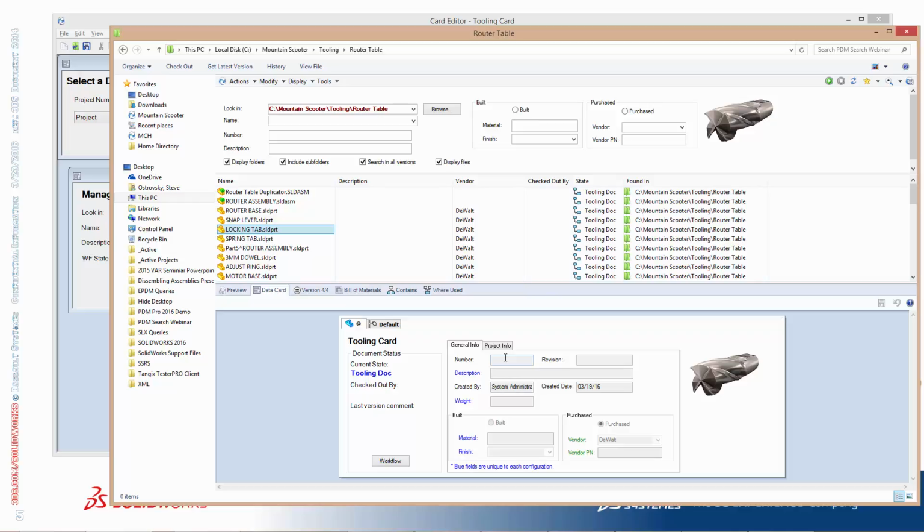I actually built one for a customer last year, and on their tooling, we created about 3 or 4 different tooling searches. Lathe, mill, and a couple other ones. And on there, we would have the tool type, the tool holder, tool diameters, and the gauge length, along with their particular ID numbers.